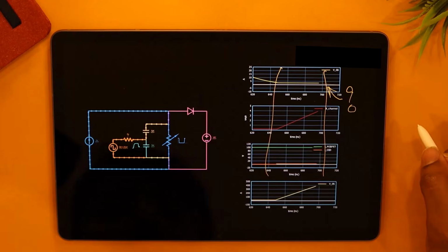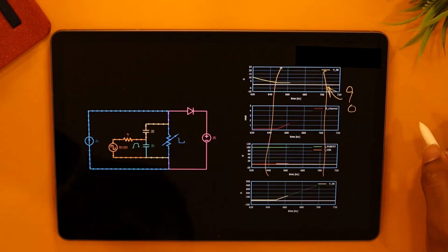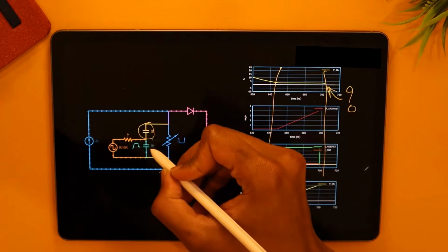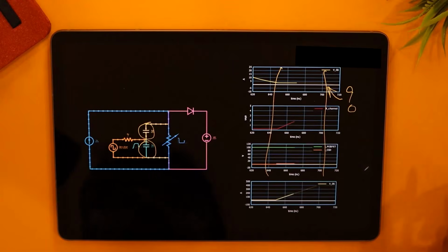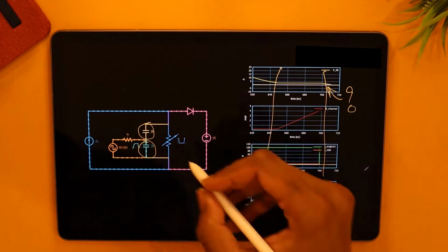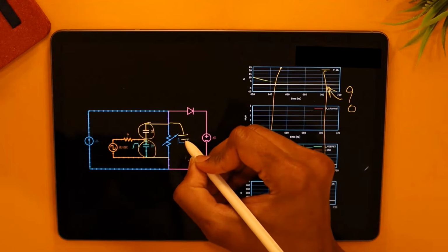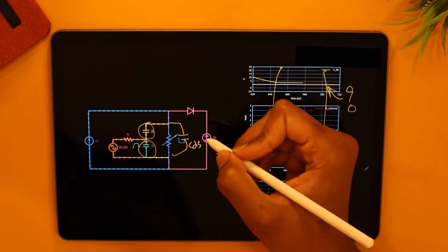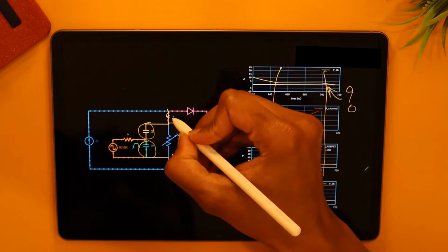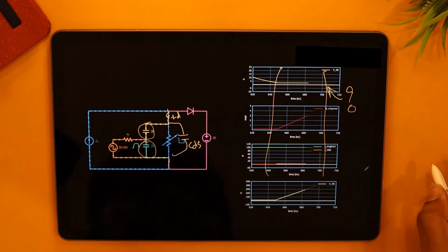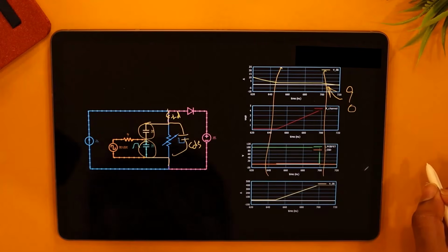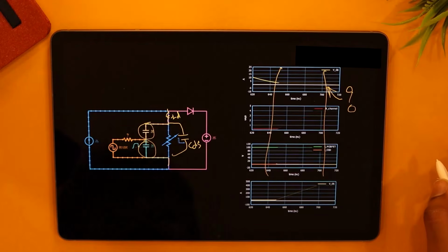One more thing, by the way. We only assumed the MOSFET to have these two parasitic capacitances, CGD and CGS, in this video, and that was enough for explaining the plateau. But what happens if you add the other capacitance, CDS, and other parasitics such as the lead inductances, LD, LS and LG? How do they impact the switching behavior and switching losses? So there are a lot of questions still to be answered, and we are going to tackle all of them in the upcoming videos.